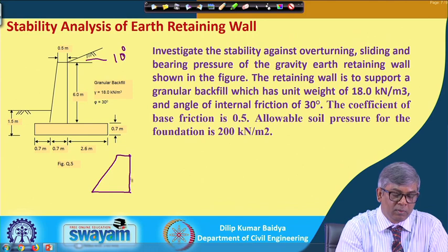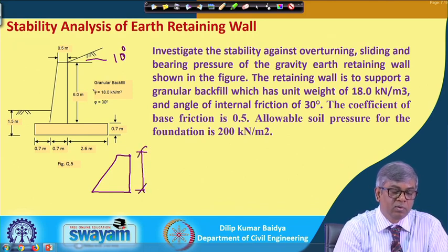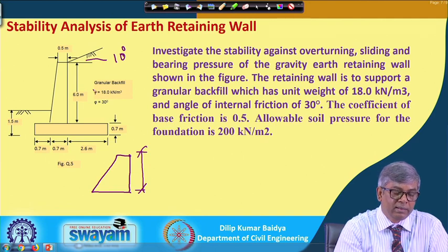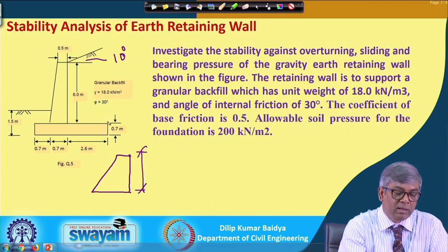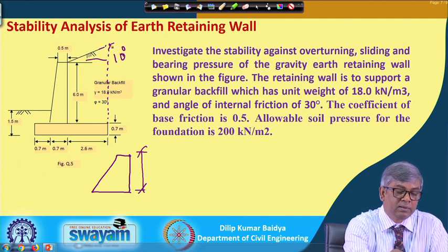Whatever the height of the wall, this is the wall height, but when there is a sloped backfill, what we do is, from the end of the vertical wall we draw a vertical line, and you can see it meets the backfill soil surface here. So I will imagine the wall from here to here, this is the wall height I will imagine.